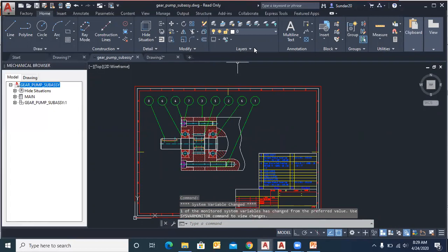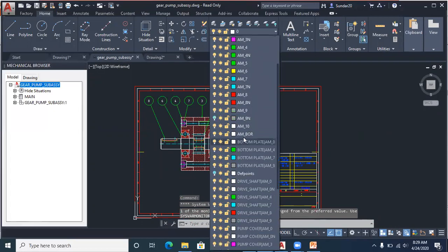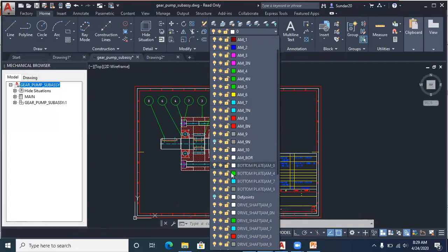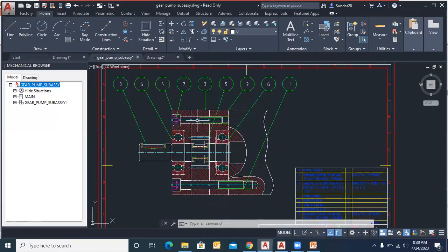Here in this drawing, you can see the predefined set of layers, which start with AM, for AutoCAD Mechanical. It already took them from the standards, and the other standards, like how we create in plain AutoCAD, we are also able to create on our own. So it has that flexibility also. Okay, so we don't need to go with only these mechanical layers provided with AutoCAD Mechanical, we can also create our own layers inside this layer management. So it's more flexible compared to AutoCAD.